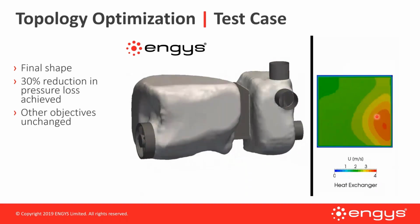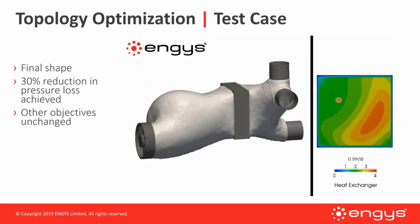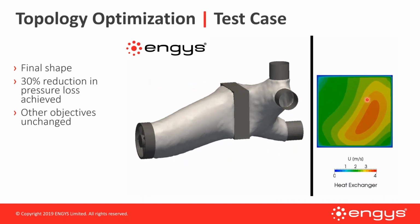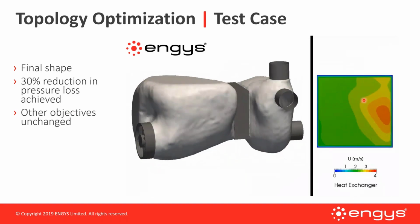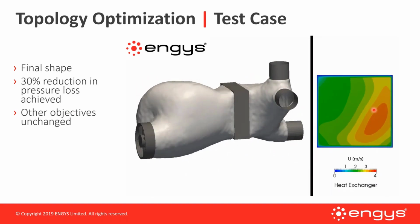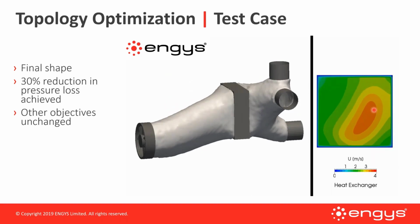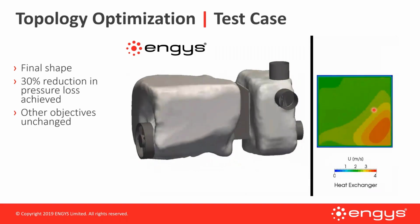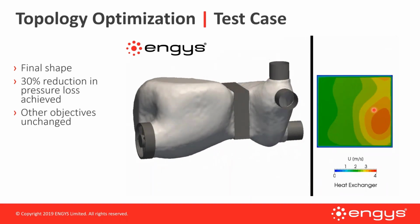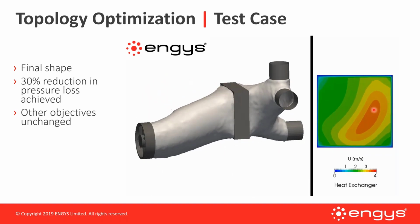We do see increased uniformity within the heat exchanger. It's not completely uniform, so there was a little bit of a cost of being able to balance these three and minimize pressure losses, of not having necessarily the best uniformity within the porous media. So this is a great example of when you perform a multi-objective optimization, you have to prioritize which one of these objectives matter the most, because we weight the influence of each one of these.